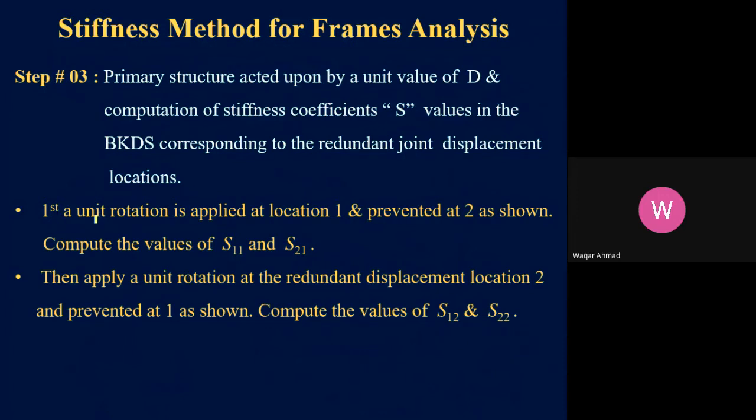In the first step, I will apply a unit rotation at location number 1, and due to that unit rotation, there will be some moments induced in the members, and then I have to find out the values of the fixed end moments which are due to this unit rotation.